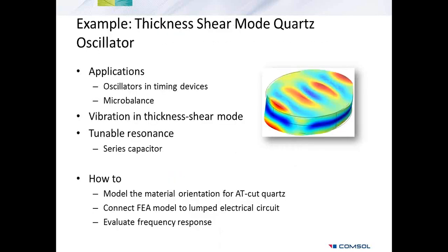Quartz oscillators. They are commonly used in many devices such as clocks and microbalance for high precision measurements. In this particular example, we are interested in modeling the frequency response of an AT-cut quartz that exhibits vibration in shear mode when electrically excited across its thickness. The response is tuned by adding a capacitor in series with the piezo device.